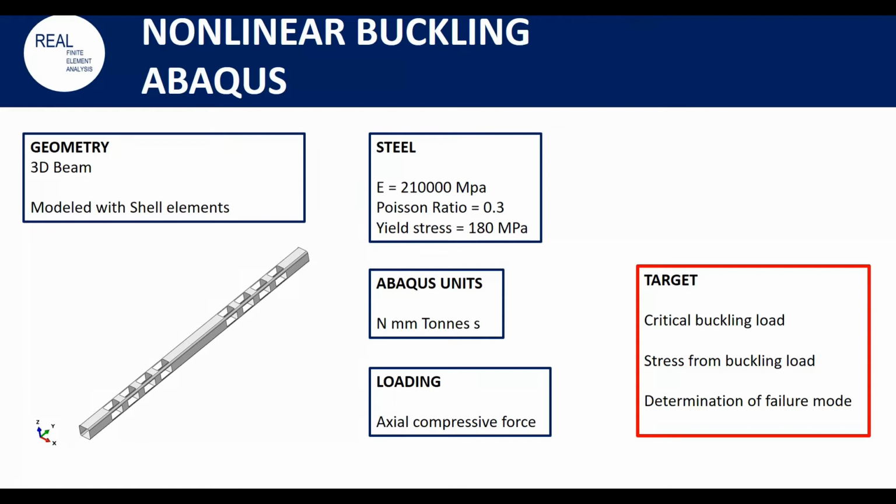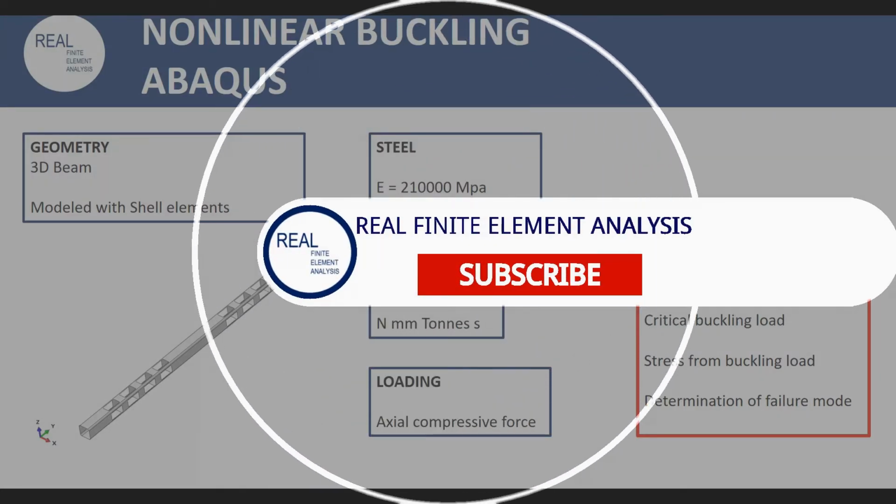I need to say as well, on symmetry: for nonlinear buckling, we can't use symmetry. So although this beam will be symmetric, we cannot use that. It's not recommendable. And this is the introduction to this exercise. So we will move on into the Abaqus platform.